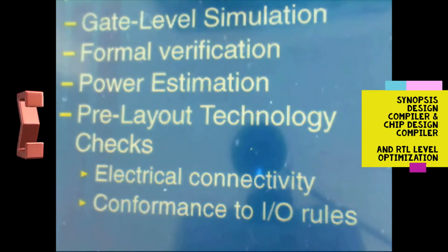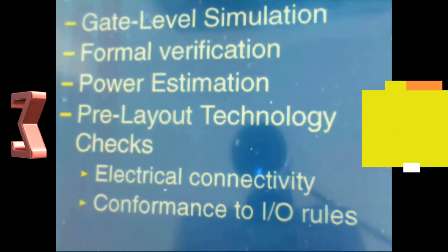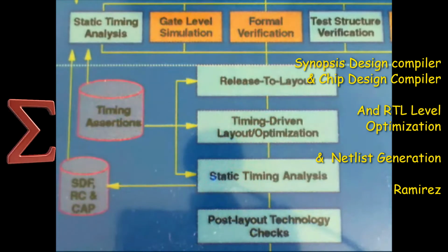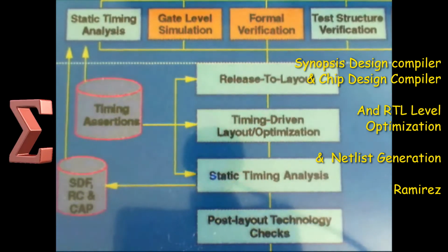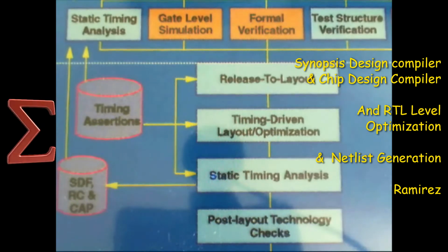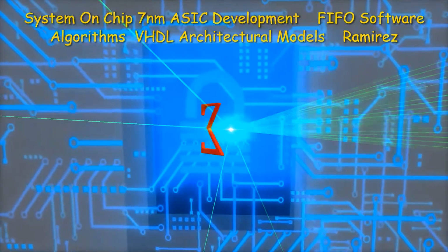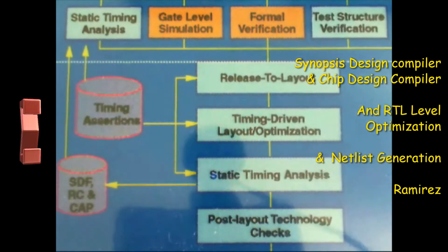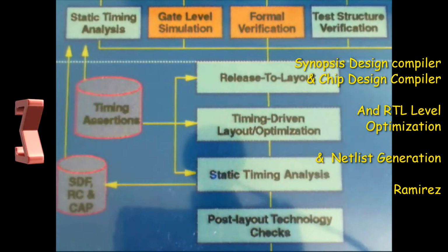The design compiler uses technology libraries, synthetic or DesignWare libraries, and symbol libraries in order to implement synthesis and to display synthesis results graphically. During the synthesis process, the design compiler translates the HDL or VHDL description to components extracted from the generic technology GTECH library and DesignWare library.